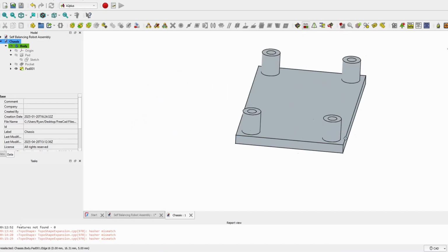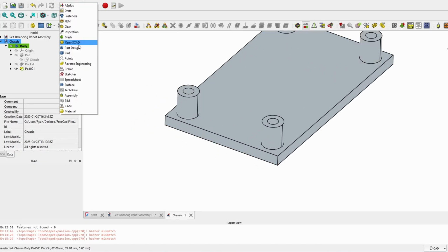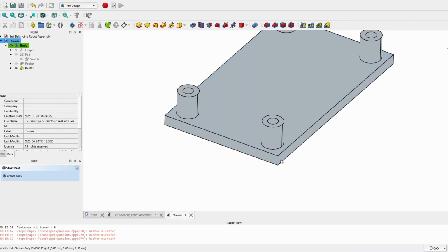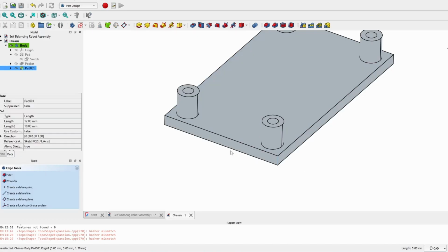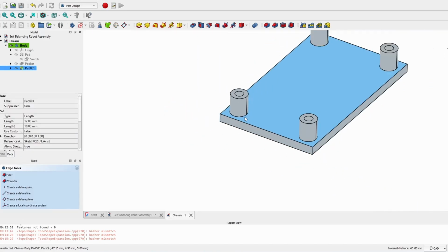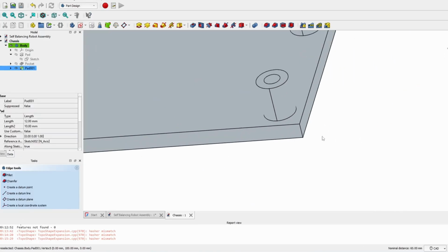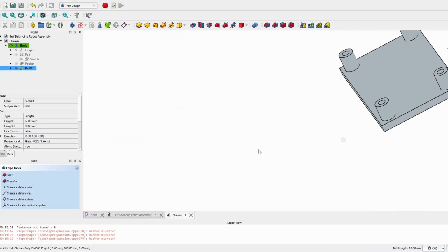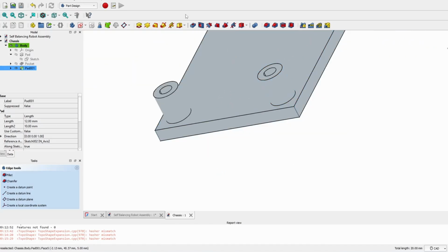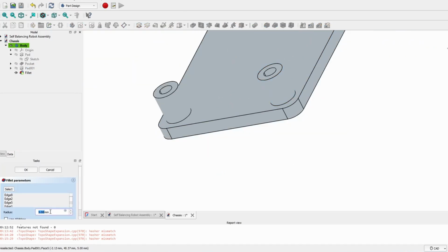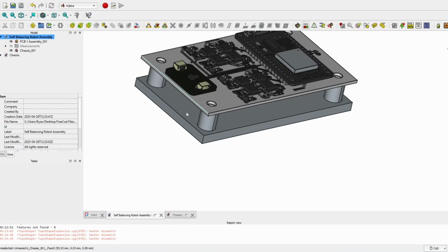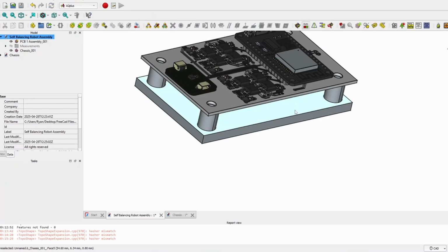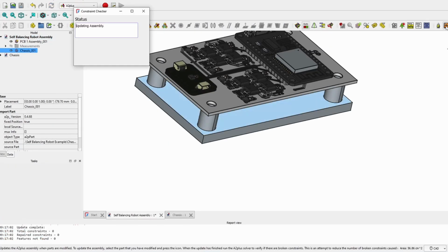And of course you can make your object look nicer and less sharp on the edges, because that's pretty important as well. So you can select your edges. I'm selecting multiple edges, again, using the control click, and then you can fillet your edges like that. And then you can just update like this. And of course you can just keep doing this to make something more complex.